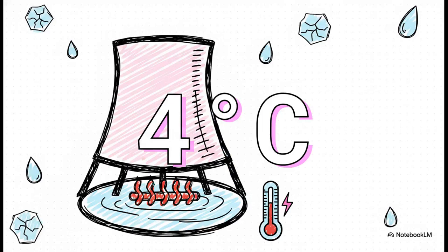Another absolute lifesaver when it comes to control features is the basin heater. This is basically a thermostat-controlled electric immersion heater that acts as a strict failsafe. Picture this: a cooling tower shuts off during the dead of winter. The water inside can quickly freeze, expand, and completely destroy the pipes. No way do we want that. So this heater automatically kicks in at exactly 4 degrees Celsius. It stops winter freezing dead in its tracks before it can take down your million-dollar infrastructure.